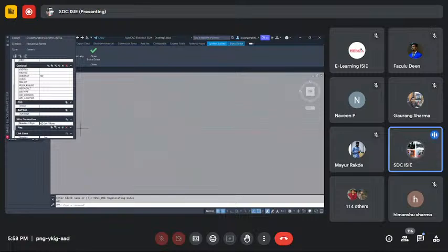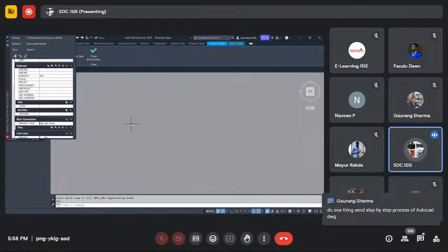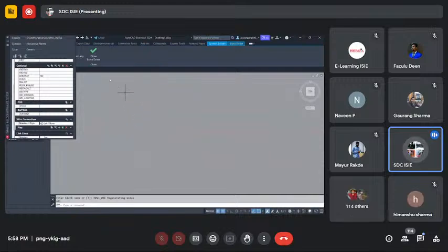For the left part, in our controller, we have more than 10 wires, like 12 wires. So we can give 5 wires on the left side and 5 wires on the right side. Along with that, at the top and center, we are connecting 2 wires for the key switch as well as for restarting the controller. So we have to make all these connections in that particular part.